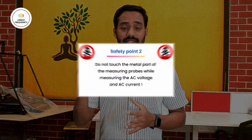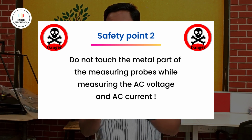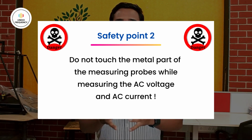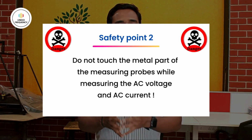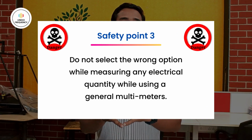So that's why do not connect a voltage sensor as a current sensor or a current sensor as a voltage sensor. Second one is do not touch the metal part of any electrical probes when you are measuring AC quantities, for example, AC voltage or AC current, because they can cause fatal injuries if you are not handling them properly. That's why do not touch any metal part of the measuring probes. Third one is do not select the wrong option when you are measuring certain electrical quantities. For example, if you are using a DMM and measuring an AC voltage, do not set the DMM to DC voltage.